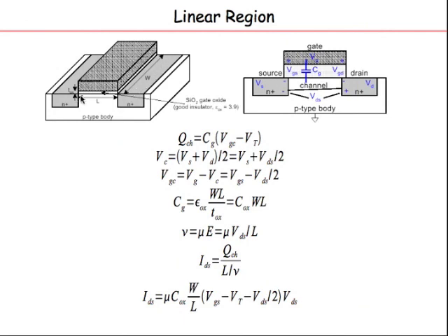As a circuit designer, what is it that you have in your control? When you design a circuit, what does it mean? Of course, you figure out the topology, how you hook up transistors. The other thing you have to do is decide the sizes of the transistors. What do you mean by the sizes? For a circuit designer, it's essentially the channel length and the channel width. You can decide there is a minimum length which the technology will provide. That is basically, as we said, when someone says it's 130 nanometer or now 14 nanometer, you have the spacing between the source and drain to be 14 nanometers. That is a minimum. You can't go lower than that, but you can go higher than that. We'll see. And similarly, width is completely in your control.